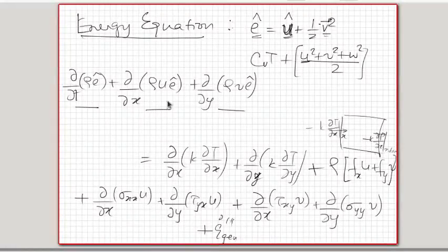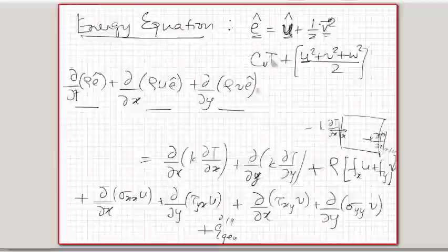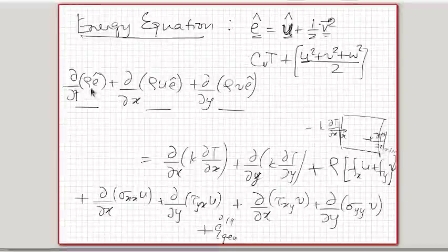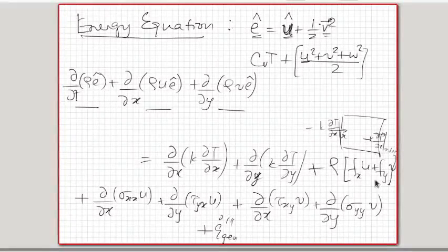Okay, so in two-dimensional conditions, the inflow and outflow would combine into this term, right? So del by del t of rho E, which is the rate of change of the specific internal energy per unit volume, multiplied by delta x delta y. Okay, so everywhere delta x delta y would get cancelled, and these two are the net inflow and outflow of energy due to advection. So this becomes equal to, what are the terms that would come?